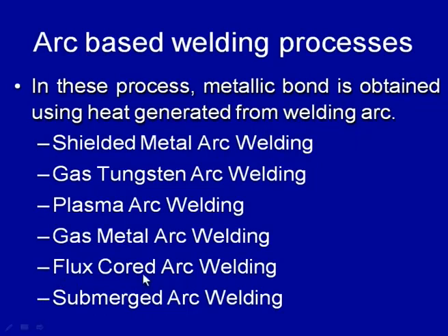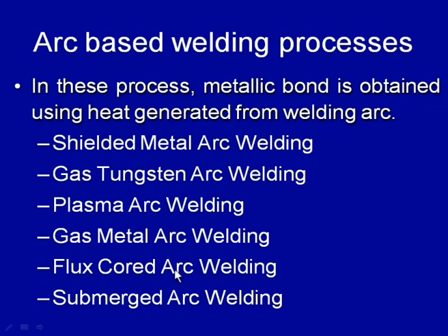While in case of flux core arc welding, the process is similar to the gas metal arc welding process, but with the difference in the sense that the electrode has a flux filled in the core portion of the electrode, and this flux decomposes by the heat of the arc and provides the cover or shielding to the arc and the weld pool by the inactive gases.